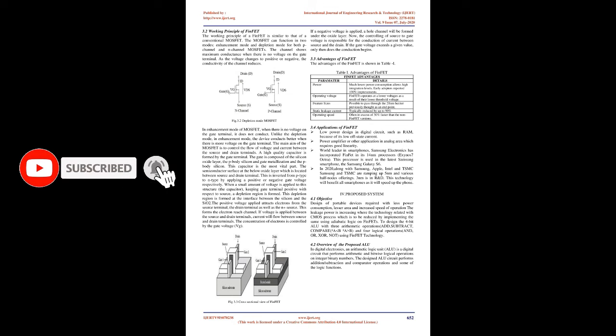CMOS technology scaling has been a basic key for continuous progress in the silicon-based semiconductor industry. Scaling has followed Moore's law for a few decades, which provided simple rules for transistor design to increase circuit density and speed. The improved circuit performance and density enable more complicated functionality, since more transistors can be integrated on one single chip. However, as device scaling continues into the 21st century, it turns out that the historical growth, doubled circuit density and increased performance followed by Moore's law, cannot be maintained only by the conventional scaling theory.